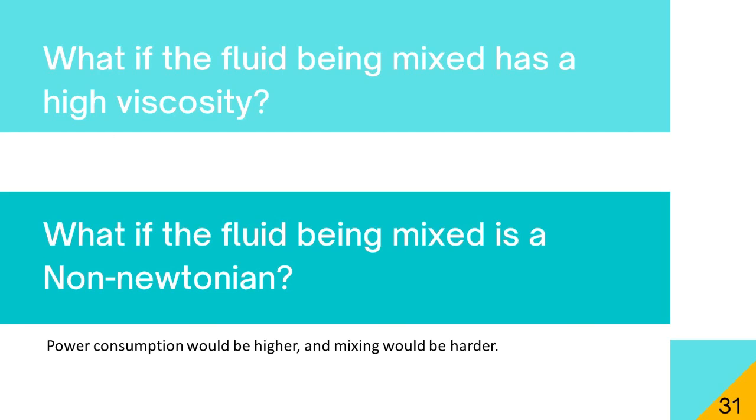If a fluid with a higher viscosity is mixed, it is expected that it requires a greater amount of power since it is necessary to apply more force to be able to cut the fluid. The flow would follow the same behavior patterns as the water in the impeller and there will be more dead zones in the upper zone of the tank.